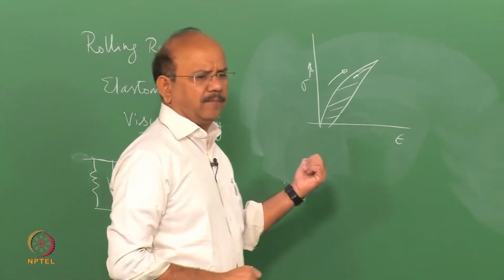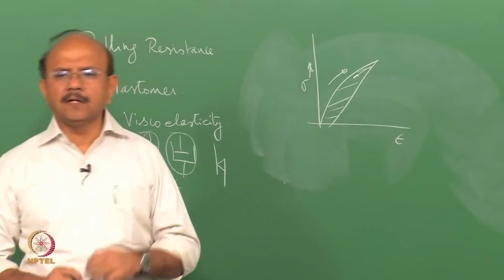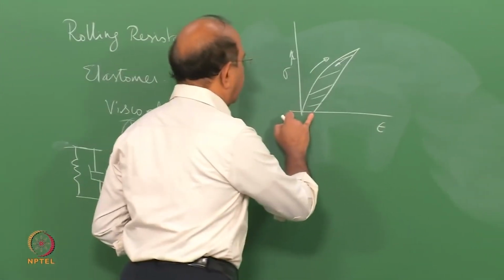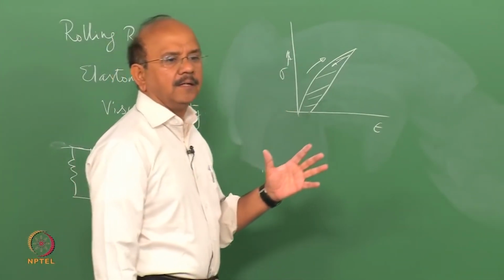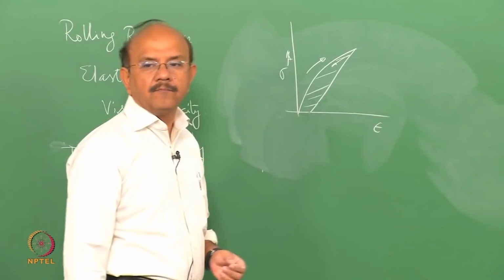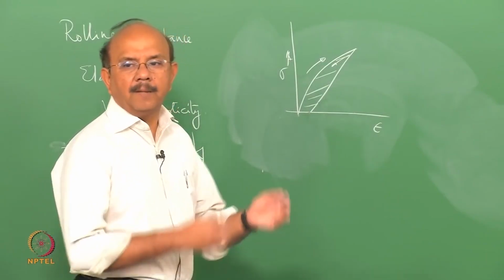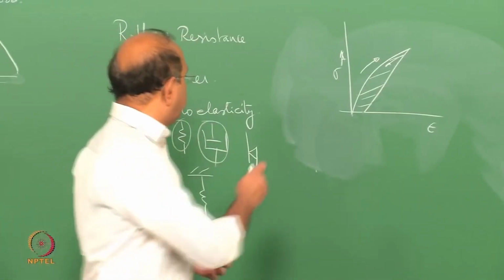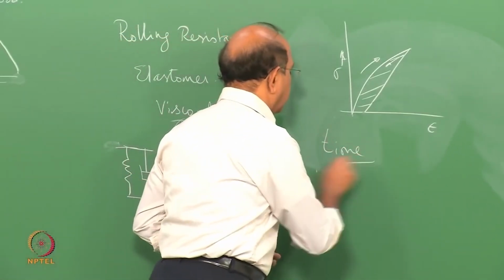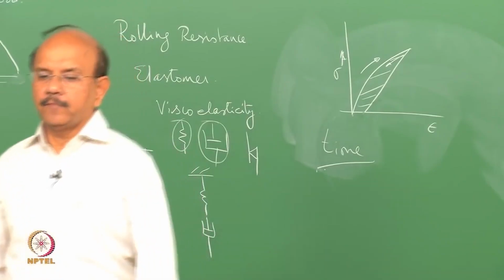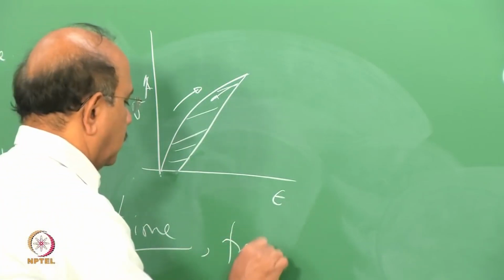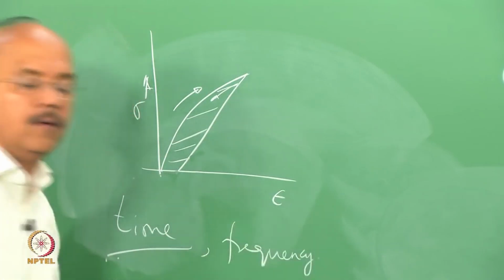It is the same as plastic, there is a subtle difference, a good difference, that though at the end of loading there is a residual strain here, the strain will come back to 0 with time. So, time is an important factor in viscoelasticity. Time and frequency are an important factor in viscoelasticity.